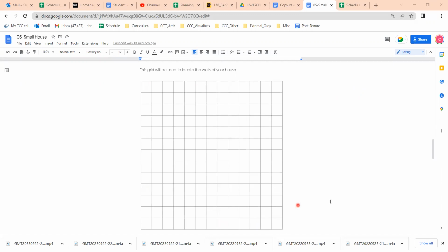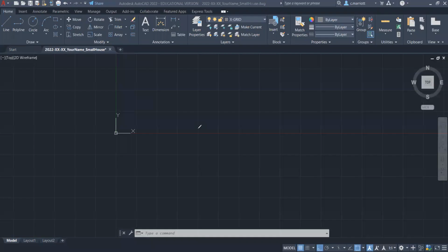We're going to create a grid that's 13 boxes wide and 13 boxes high. Each of these is 44 inches wide. So our total square dimension will be 47 feet, 8 inches. So I'll go to AutoCAD and we can continue work towards this grid. Okay, I'm in AutoCAD now and go ahead and begin constructing the grid.